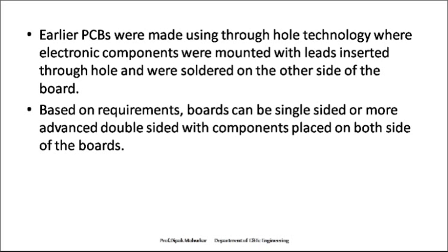This is one of the ways. Now, very small machines exist in the market, and we can make such a PCB within 5 to 10 minutes. Initially it required half an hour: we put the PCB boards in one tray filled with chemical, so the PCB is dipped in that chemical, and we rotate the tray for half an hour to 1 hour. Then the copper will be removed.